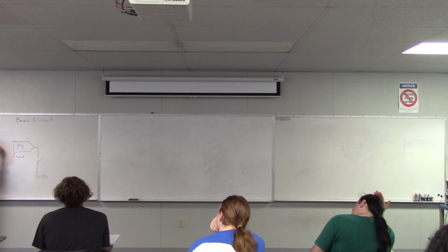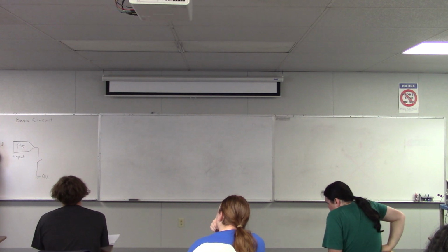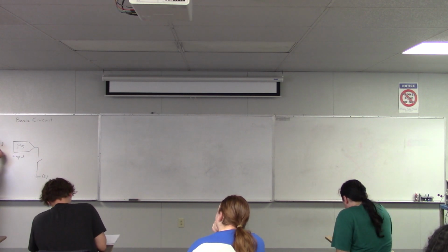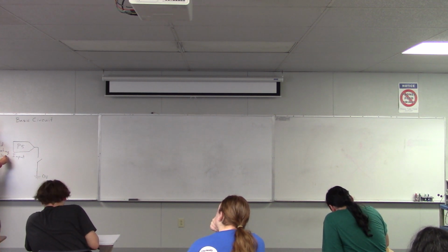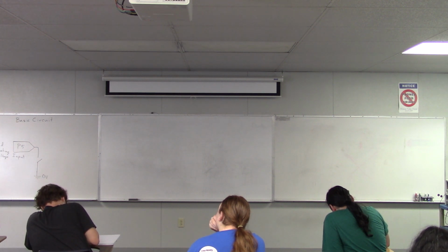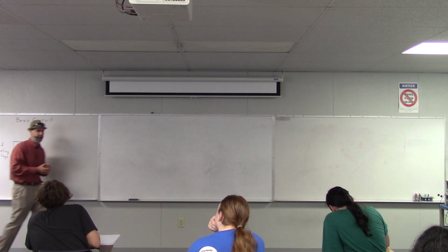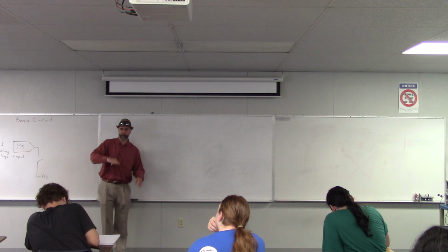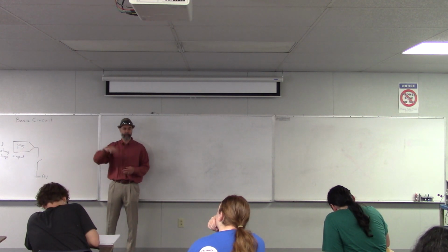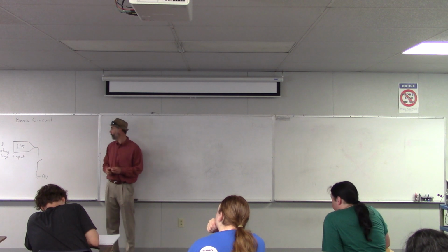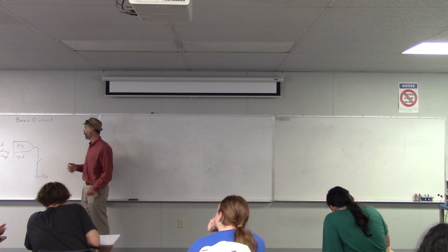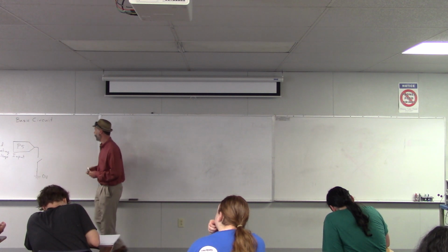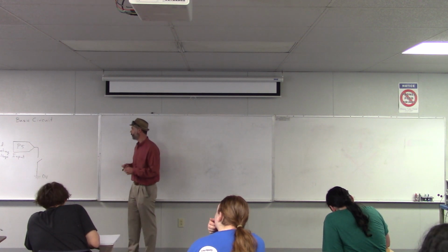So this is bad, because we have a floating voltage at that pin. When that pin is not tied to anything, that's what we call floating, because it can float up or float down at random, unexpected times. So that circuit isn't great. That's a problem with that circuit. So we need to find a solution.